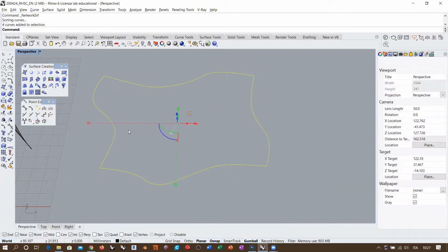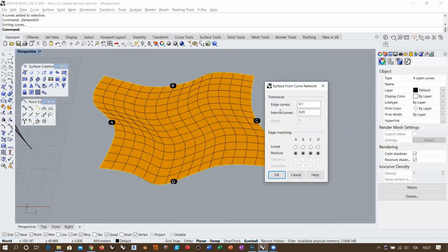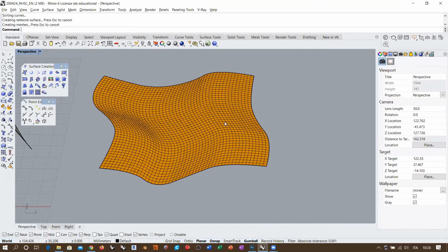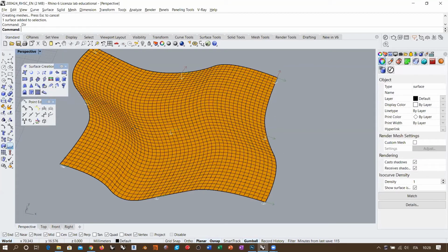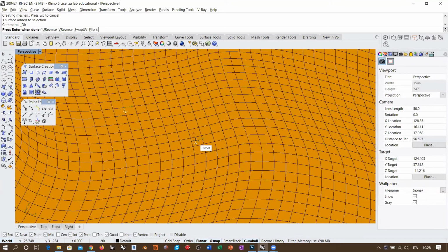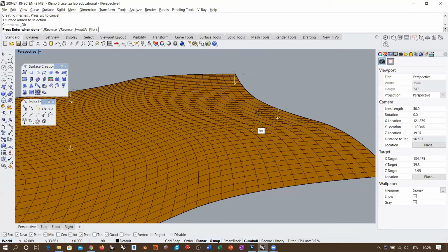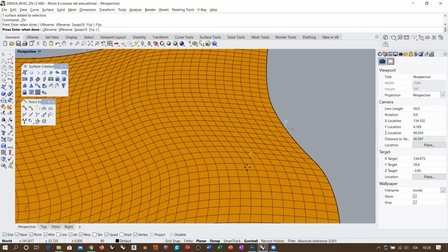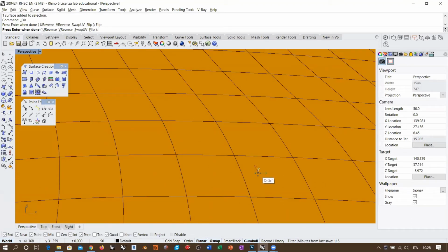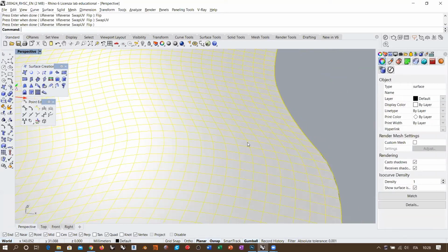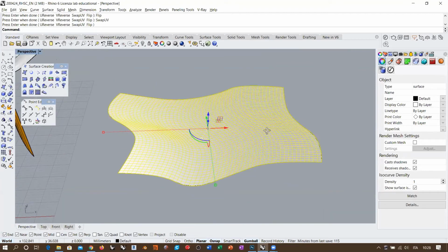Of course, I can take this object here, create the surface with the desired tolerance, eventually a very high tolerance, and obtain this object here. Eventually, I'm going to analyze this in order to bring the internal parametric coordinate system to the right orientation. So I'm going to flip the vertical direction. And as you can see, red should be pointing to the right and green should be pointing up. So I have to swap U and V in this case. And now I have the correct internal coordinate system and I hit enter. Okay. So I have reoriented the surface in order to have the proper orientation.